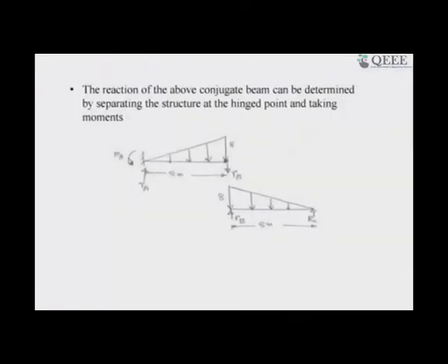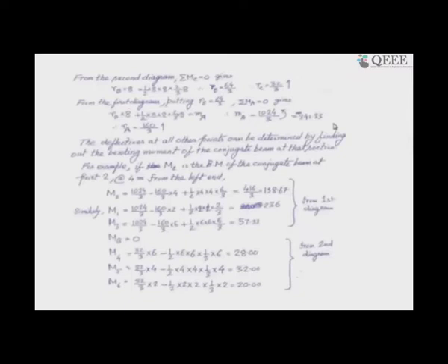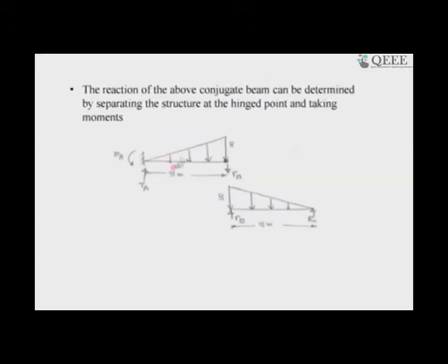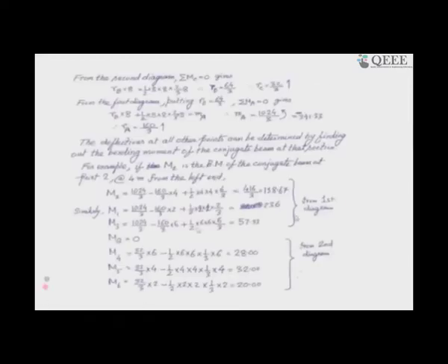Now, come to our slides, what we are exactly doing. Here, in the indeterminate structure, we are with the conjugate beam method, and then it's simple. I will not discuss any more. You just sit at a section, then come from the right at different sections, and from the conjugate beam you find out the bending moment of that conjugate beam at those sections, and you are ready with the deformations or the deflections.